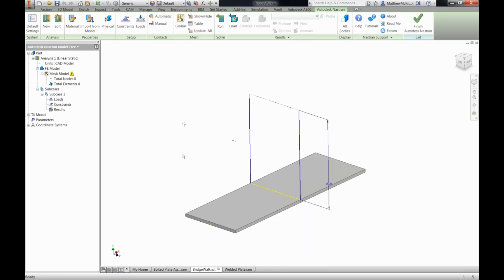The good thing here is that we don't need very complex geometry to be able to analyze and understand the interaction of this walkway. And the way that we're going to define it is we've got a plank essentially, and we're going to define it as a thick solid structure with two cables, and we'll have a pinned or hinged support at this end, so it'll be cantilevered at the other end, and we'll place a weight at the other end along with self-load to understand how this walkway is actually going to react to our loading.